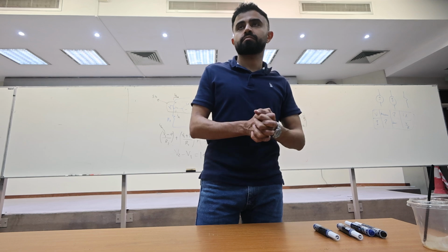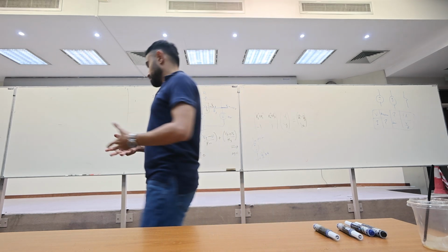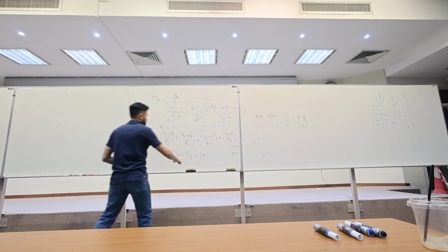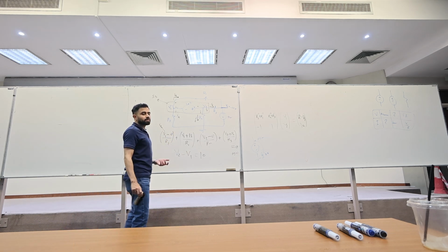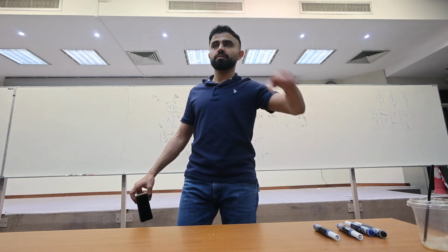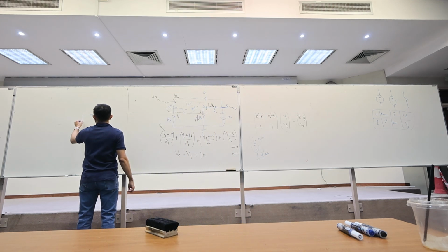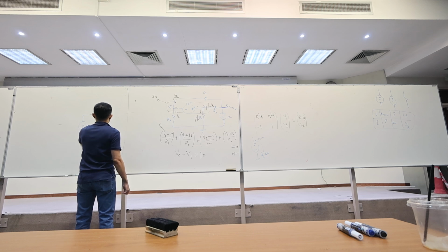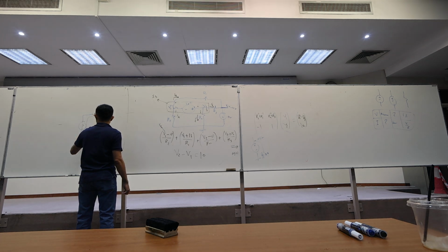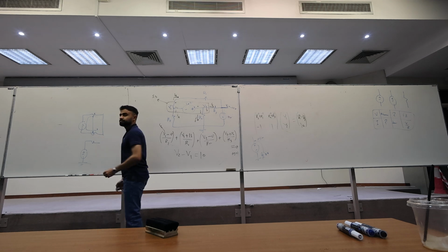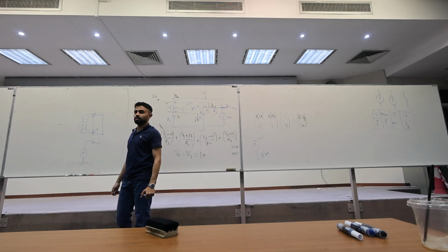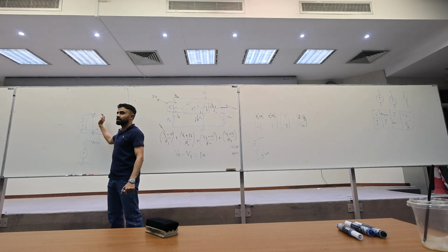I have a question about how to identify the nodes far from the source. The homework was hard. Well, it wasn't hard. I think you're talking about the homework that has a 3 at the bottom, question number 2. In the homework you had a resistor, a battery, and a resistor. Are those elements in series? Yes, they carry the same current. So you can combine this resistor with that one and make it simple. This was the trick. You need to simplify that branch.